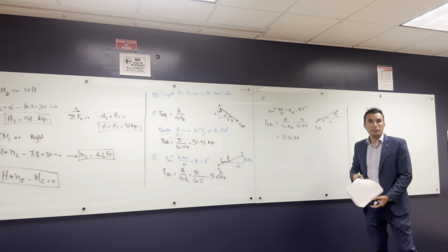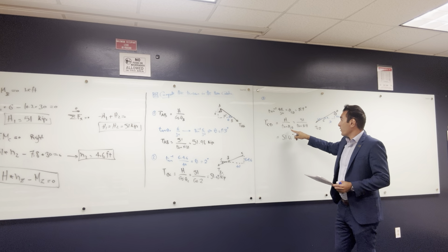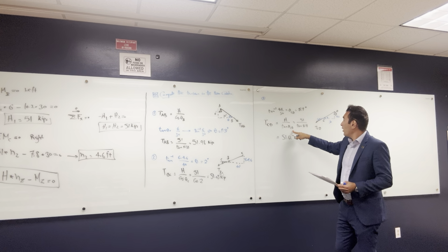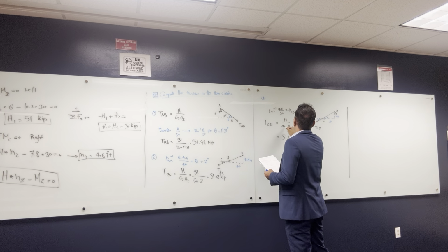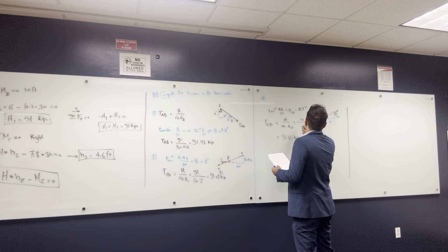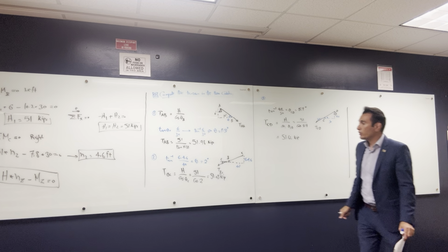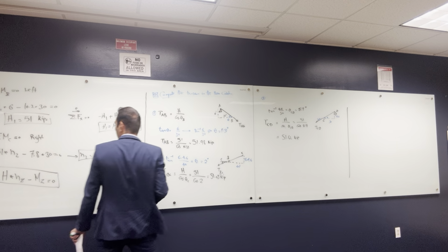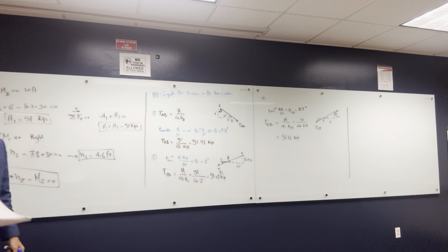Does anybody have any question? Is that H over tangent or H over cosine? This one? H over tan theta CD. I thought that's supposed to be cosine. Oh, sorry, yeah, that's cosine. The tan is to get the angle. I put tan here, but the numbers are right. This one is cosine. So I got all the forces in the cables.